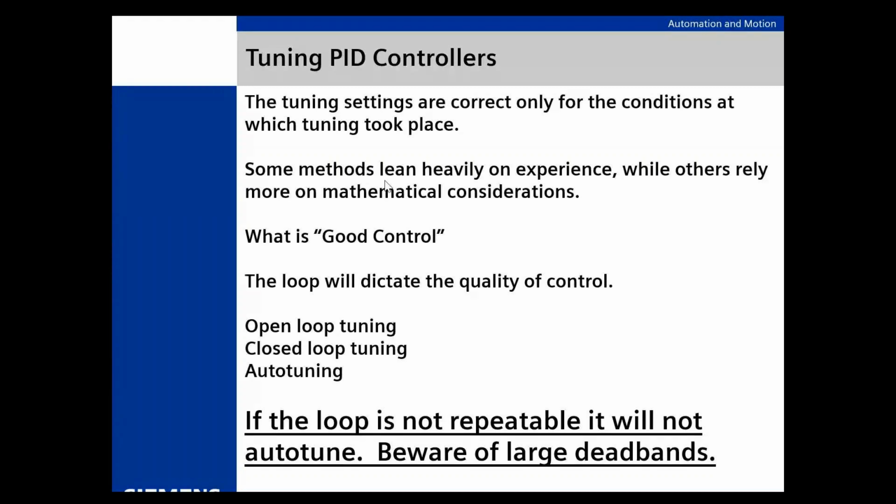Pick a place and add it. When you add it in both places, you're really not going to get good control out of that. And a lot of people don't know somebody did something in the field, so they don't really know what to do with the control system. I personally prefer to pick a place to do the dead band, be it in the system, the controller, or the field, and go with it. That's at least a little standardization there. Then I know what to expect.